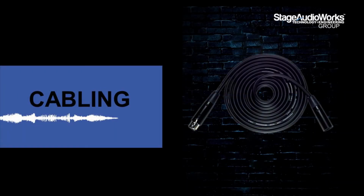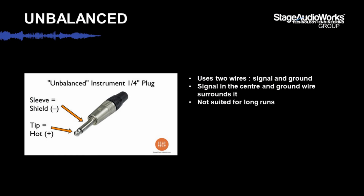In cabling, we're going to talk about two types of audio circuits, namely unbalanced and balanced. So unbalanced. An audio cable carrying an unbalanced signal uses two wires, signal and ground. This is how, if you look at this picture here, your typical guitar cable is built. For example, a TS guitar cable stands for tip and sleeve. The wire that carries the signal is in the center, and the ground wire surrounds it.